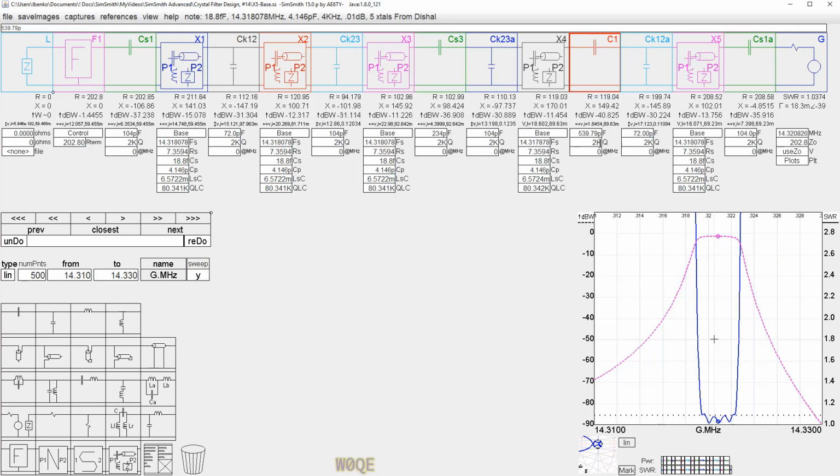Well, I'm kind of wrong on that one. Let's go a little bit higher yet. 300 hertz. That's correctable too. So this pretty much says to me, if I had crystals, I'd sort on C sub S primarily. I'd take the two lowest in frequency that were pretty close to the same frequency together, because you don't want to correct these too much, I don't think, crystals 2 and 4.